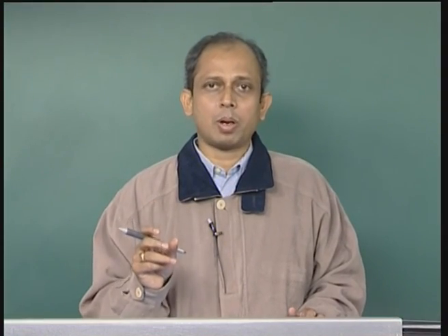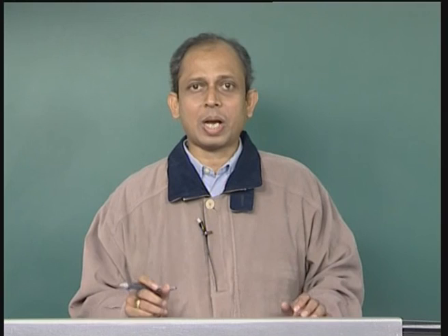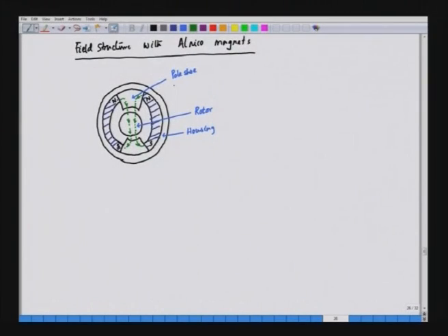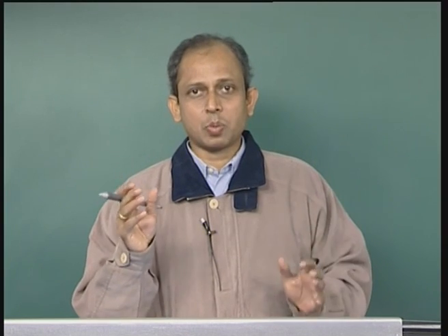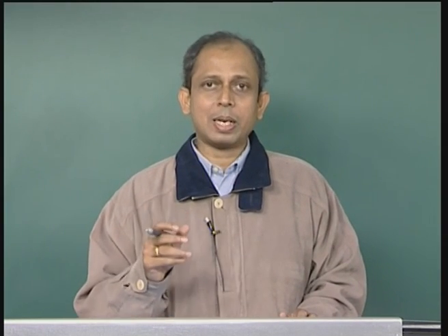Now, in all permanent magnets, we should remember that the permanent magnet materials are very brittle and cannot be easily machined. This gives this kind of long magnets which can be fitted in the soft iron. The pole shoes are basically soft iron and the magnet is long and a little curved, and it is fitted in the stator housing with the pole shoe, so that ultimately it creates north pole and south pole as we have seen.